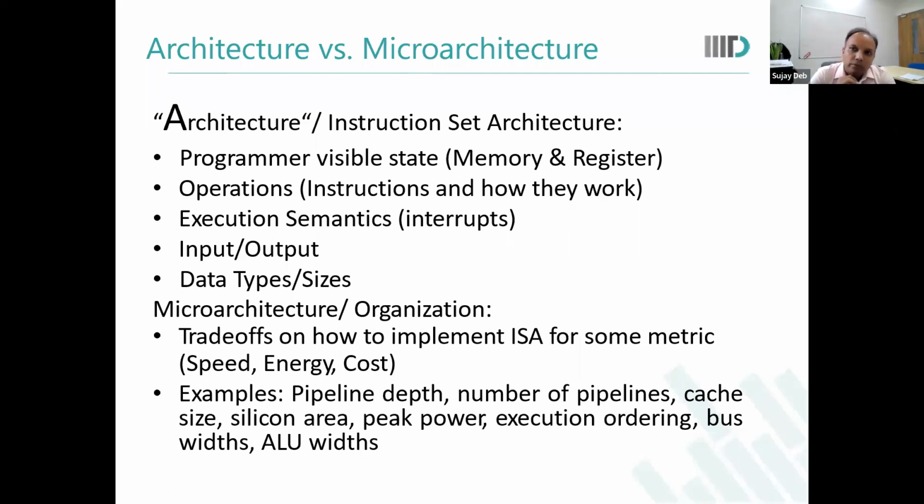See, there are a few thumb rules. I would not call them standards. Generally, you have either a 64-bit processor or a 32-bit processor. Depending on that, you will define what link width you will be using, and then the router. Again, you want to make the router as simple as possible, and many things depend on the kind of topology you select. The topology I showed was a mesh topology.